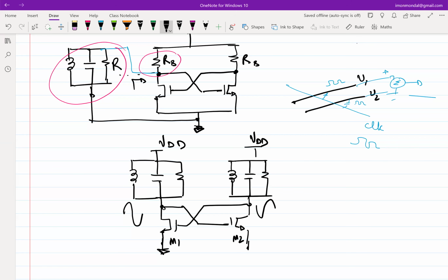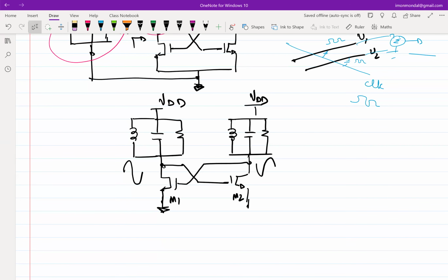Okay, fine. This type of circuit is often called a voltage controlled oscillator, right? Okay, I shouldn't say voltage controlled because I have not talked about what is voltage control. These are just oscillators for the time being. Why is this an oscillator? Because it's generating an output, a signal, with no apparent input. It's oscillating on its own. It's like a simple harmonic motion or a pendulum which keeps on oscillating forever without any apparent input, right?